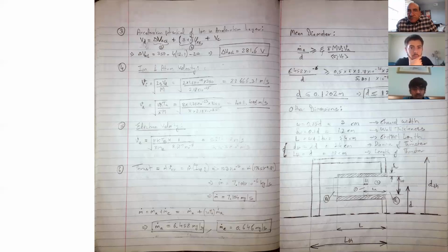Okay. So the thrust is actually m dot v. That's a very common formula. And v, the exit velocity, is given by the ISP times g. ISP is the specific impulse, and g is 9.81. So I equated the thrust, which is 123, which I assumed in the beginning, equal to m dot times ISP times g. The ISP is also known, the specific impulse is 1765.